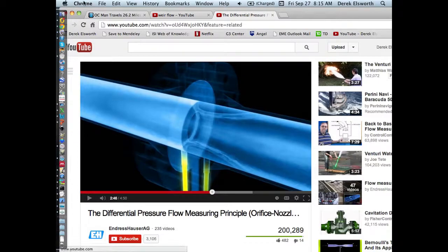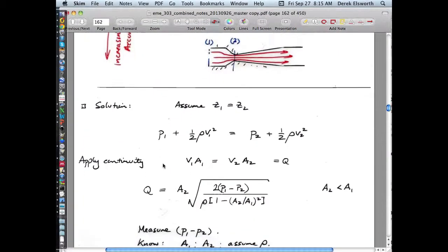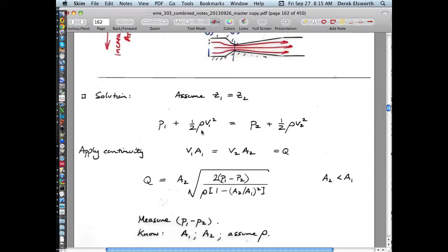For now, okay. So the expression comes then from writing the equation at two points, upstream of the Venturi constriction and downstream of the Venturi constriction, noticing that in this we have two values for velocity, which we can link if we write them in terms of the volumetric flow rate.